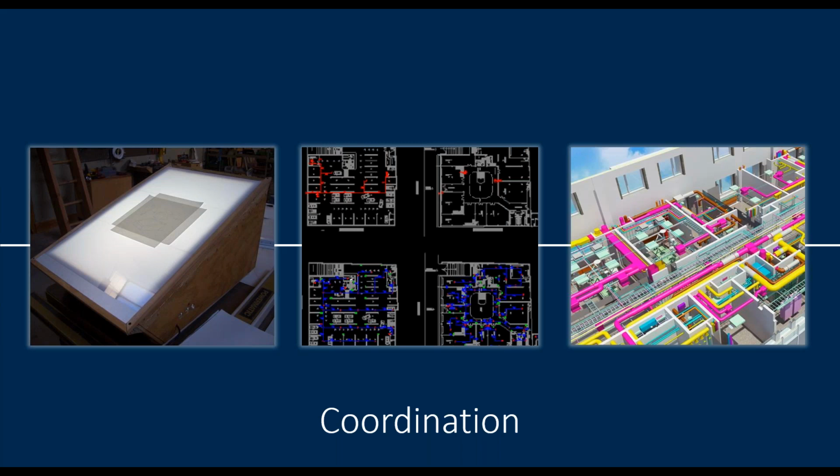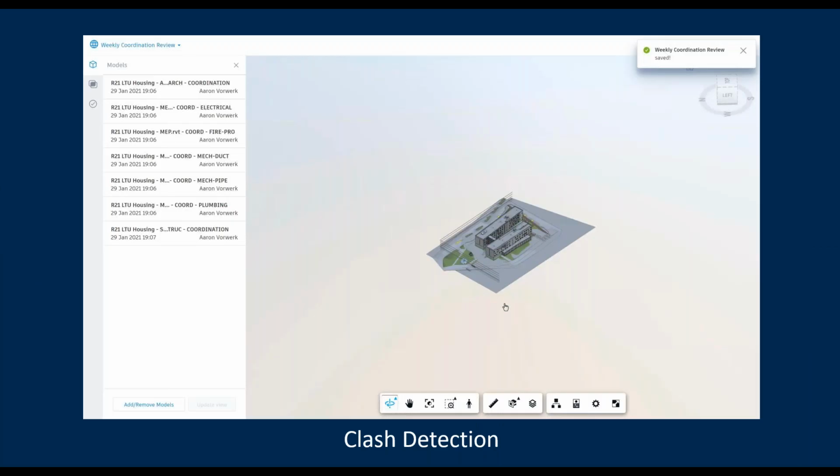And what's really nice with the 3D tools that we have available is that you can colorize the various objects, and this just helps you to identify clashes a lot easier. And so let's look at what that looks like. So what you're seeing on the screen is a snip from the model coordination module from the Autodesk Construction Cloud. So this would be the newer products that have been introduced since April this year. Previously, you might have known BIM 360 Design or BIM 360 Glue, those things.